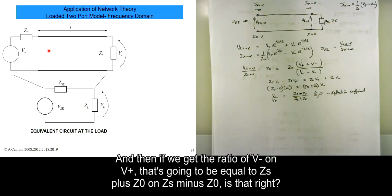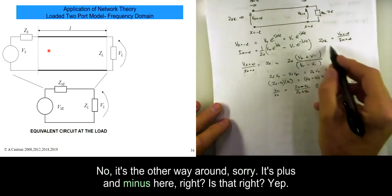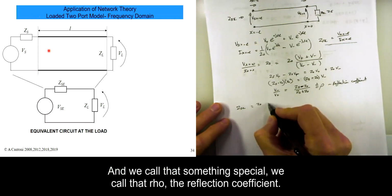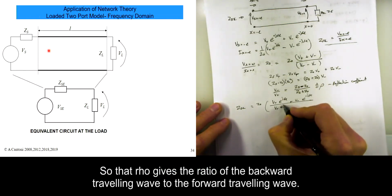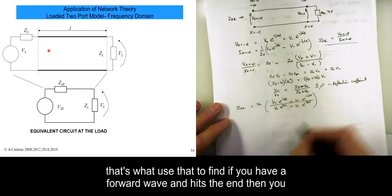equal to what's it going to be equal to? ZS plus Z0 on ZS minus Z0. Is that right? No, it's the other way around. Sorry, it's minus on top and plus here, right? Yep. And we call that something special. We call that rho, the reflection coefficient. So that rho gives the ratio of the backward travelling wave to the forward travelling wave.